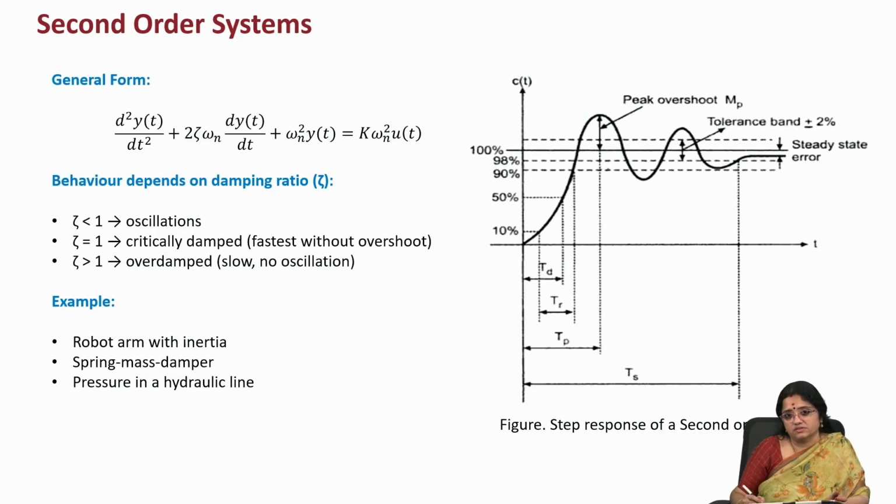Moving on to the second order system, as we discussed earlier, the order of the system is the order of the differential equation, which is 2 here. The highest order of the differential equation is 2, which is why it is termed a second order system. Analogously, when looking at a physical system, any system having at least two accumulating devices, mass accumulating devices or energy accumulating devices, can be approximated to a second order system model.